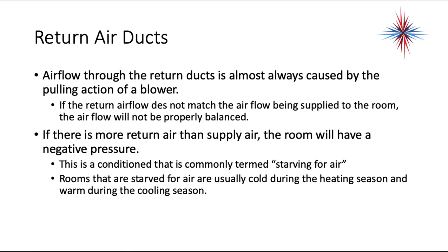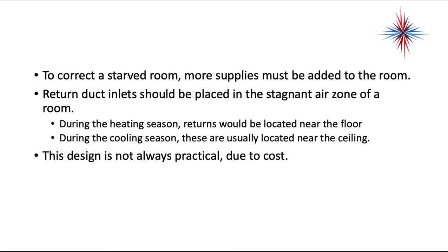On the return ducts, airflow through the return ducts is almost always caused by the pulling action of a blower. If the return airflow does not match the airflow being supplied to the room, the airflow is not properly balanced. If there's more return air than supply air, the room will have a negative pressure, and this condition is commonly termed starving for air. Rooms that are starved for air are usually cold during the heating season and warm during the cooling season. To correct a starved room, more supplies must be added to the room.